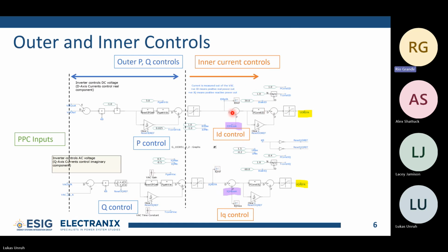So in your phasor domain, all the stuff on the left is going to produce a current reference, and that current reference is going to be exact. It's basically imposed on the grid, directly injected without this detailed control loop. So this is a major distinction between the phasor domain and your EMT dynamic models.